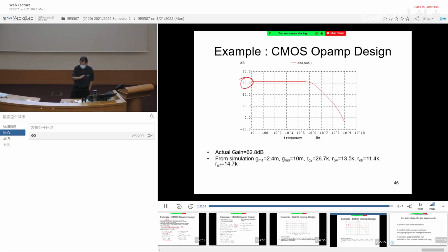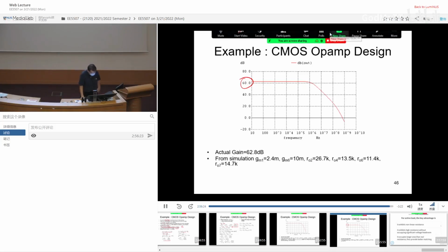The first thing you do is power budgeting. Okay, you decide how to split the current. As long as you can make your justification, that's fine. Okay? And be assured, you can never get the result right away. Okay, but that will bring you to a close enough result. And then you fine-tune using the simulation. Okay? So that is the key takeaway. I just re-emphasize.